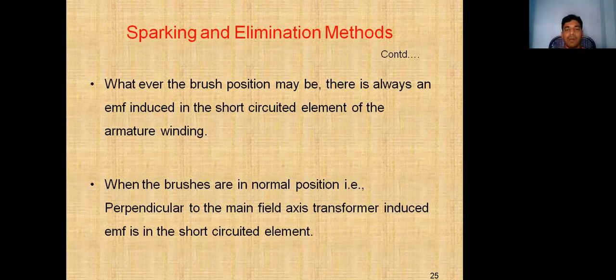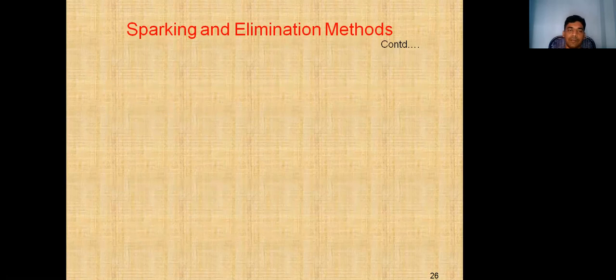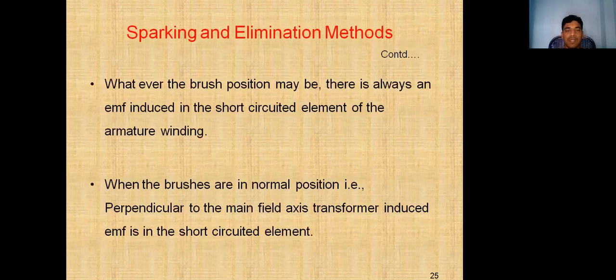When the brushes are in normal position, that is perpendicular to the main field axis, there is a transformer induced EMF in the short circuited element.